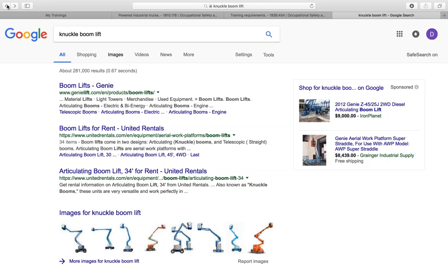And then if we're talking about safe operation of a scissor lift, what are we talking about? Now, it's a scissor lift, and we know that they use hydraulic rams to lower and raise the platform. It should be one smooth elevation up, one smooth elevation down. It depends. It may be propane operated, gasoline or diesel operated, or battery operated as well. So they all come with different sources of energy. And so we also need to be aware of the types of hazards associated with the form of energy or fuel that we're using to power that piece of equipment.